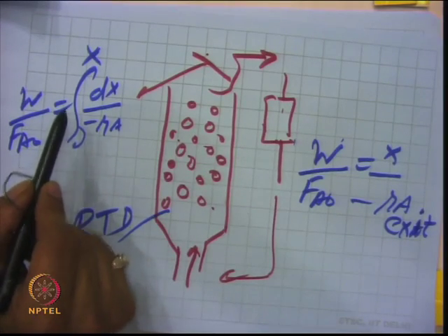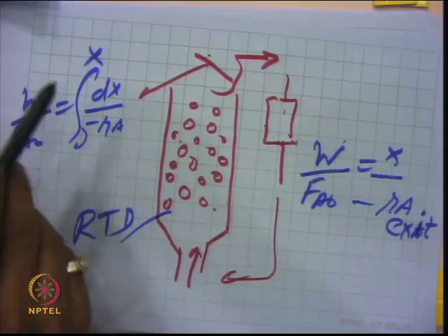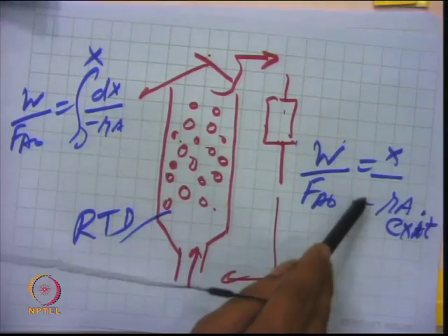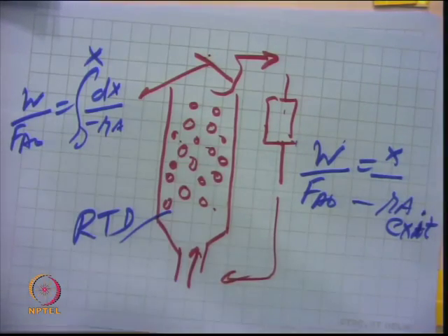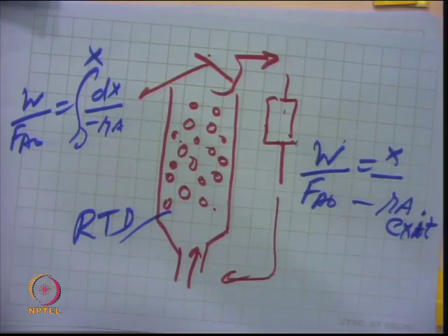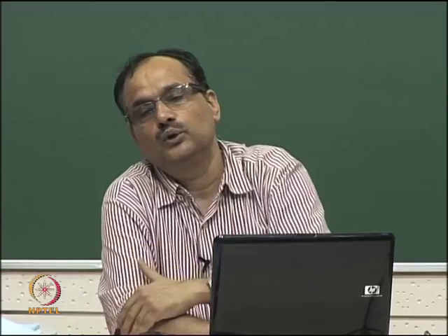unlike in a plug flow reactor. So, that is the difference in the case of a plug flow reactor, a CSTR and a fluidized bed reactor. So, you need to look at the exit age distribution and then calculate the mean conversion by measuring the fraction of the solids, their age inside the reactor, and then accordingly their conversion as per the formula, and then take the average for the total number of particles. So, that is important in the case of a fluid bed reactor.